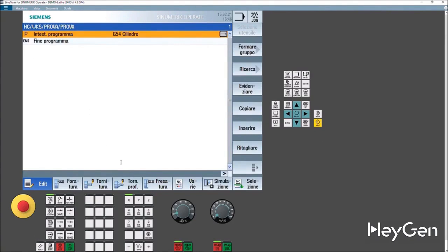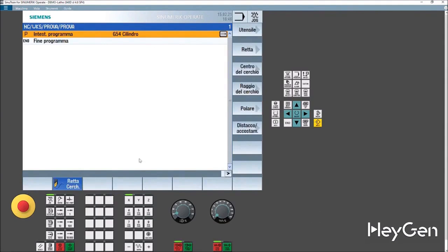Let's say I just want to chamfer with the Fanuc and manual guide. Chamfering was easier to do. In ISO, actually with ShopTurn, the ISO is almost foolproof when it comes to linear interpolations with this little program. You see here a series of soft keys, and here a little arrow. With this arrow, I expand my menu and go to straight circle. I haven't used it yet, even for circular interpolation. But first I want to do a straight line.